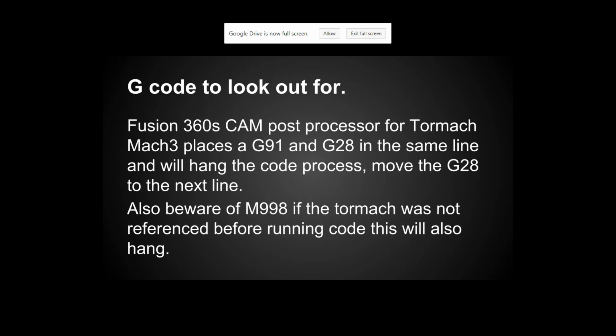So if you are using the ShopBot, I can check in a minute to see if Fusion has the ability to post-process for ShopBot yet. But typically, if you do want to use it on the ShopBot, you'll have to copy that out of a pre-existing program. There are some on the desktop on the ShopBot computers, so just copy the first 3 lines till there's a remark or pause for 2 seconds. So that'll be the first about 10 lines.